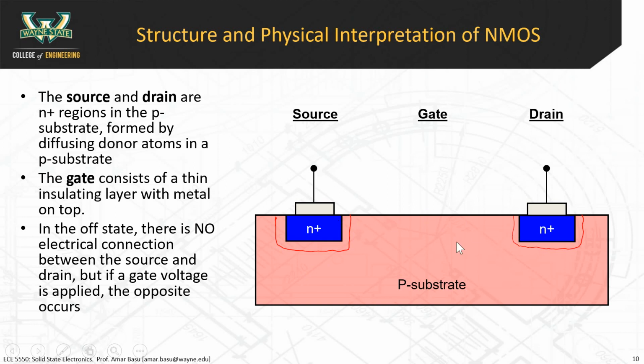So the way the gate structure looks like, the first thing is there's an oxide layer here. This is an insulating layer, okay? So it does not allow current to conduct through there. Unlike the metal being used to make a conductive contact into the N+ material, here we're specifically using an insulator, an insulating dielectric material.